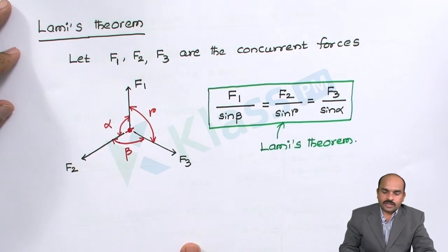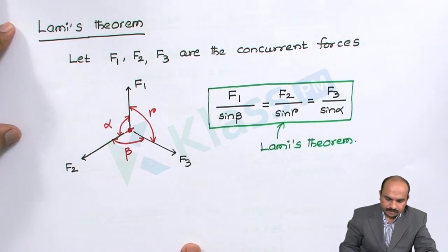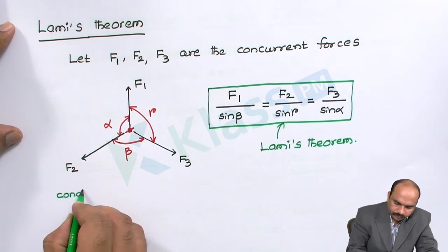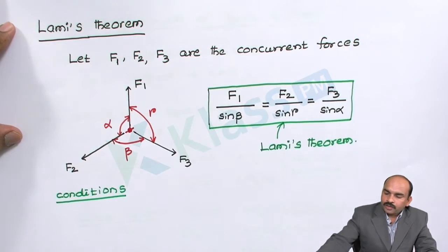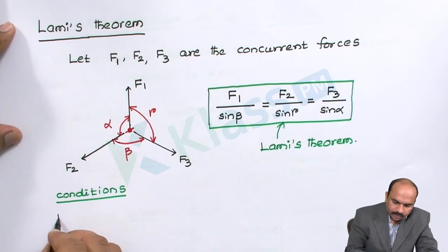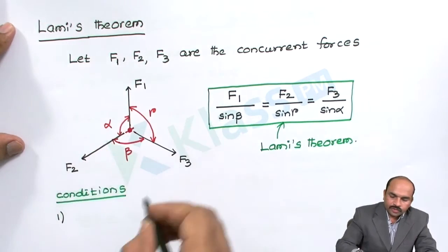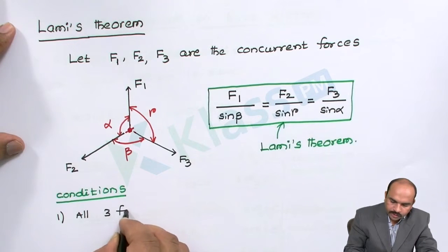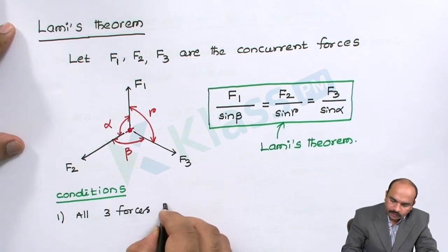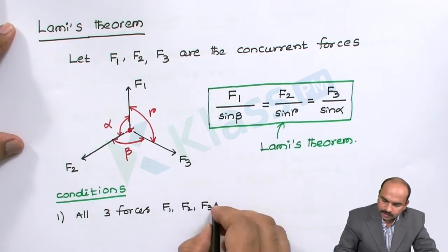In which cases can we use this Lami's theorem? Let us see the conditions to apply Lami's theorem. Totally there are 3 conditions. The first condition is all 3 forces, that is F1, F2, F3, must be concurrent forces.